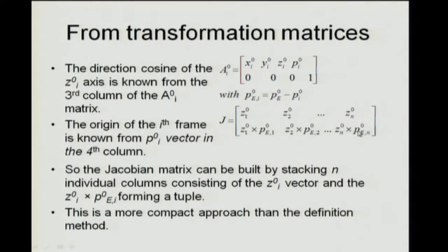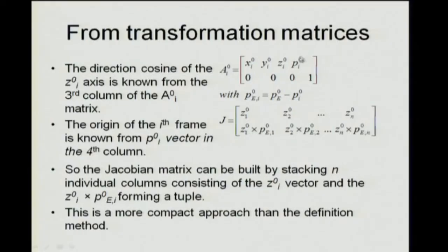So this is computationally quite simple. You have to do DH parameters anyway, to do forward kinematics, to do inverse kinematics. So you just keep on doing that, you just take out the z axis, stack it, you can find out what Pi0 is, you know where the end effector is, you know this term, just subtract, do a vector multiplication and you are in business, okay.